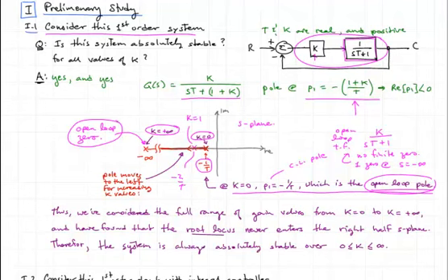Notice that based on this drawing here, we can say that this system is absolutely stable. There is no value of k between 0 and infinity that would result in the system being unstable, because the locus of poles is always in the left half s-plane. Okay, and so this whole thing here, this is called the root locus.